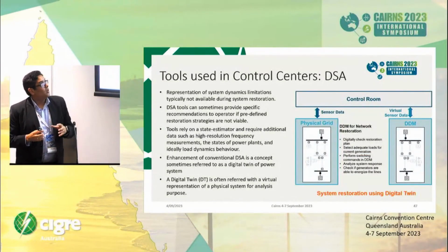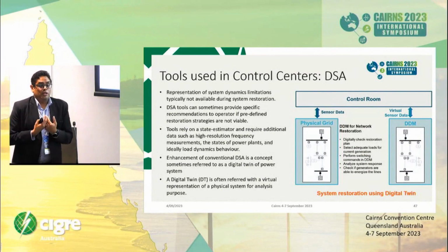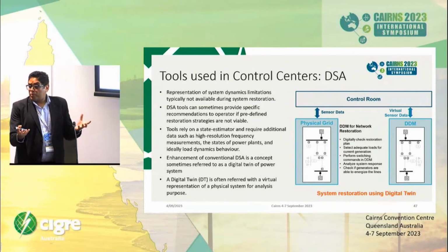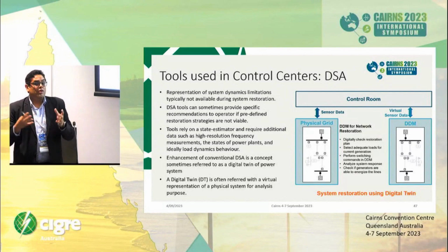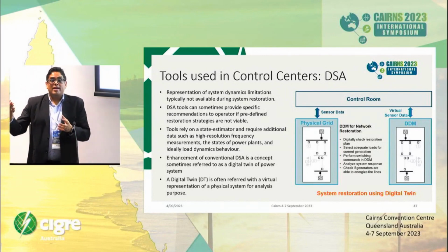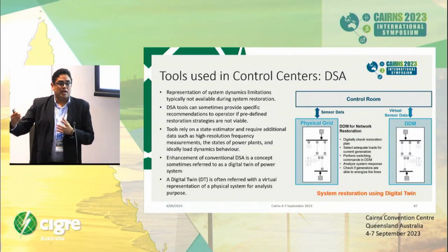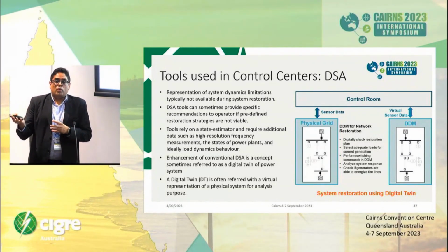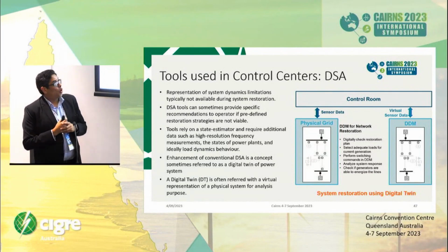The other tool operators have is dynamic security assessment. As you know, currently vendors are providing that capability where you can save your EMS snapshot and run it in an almost near real-time scenario to look at the dynamic performance of your voltages, rotor angle stability, and all that stuff. So that's one option the operators have.